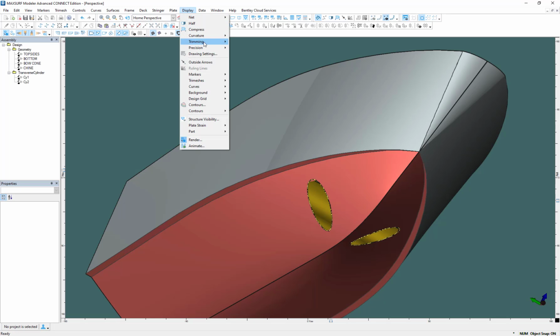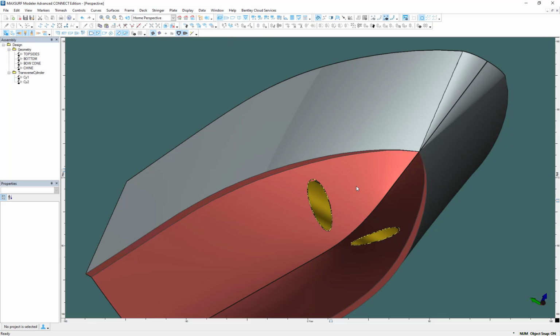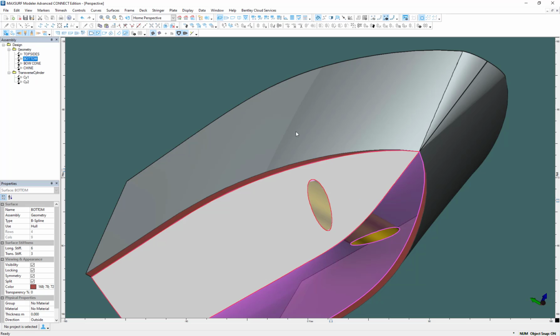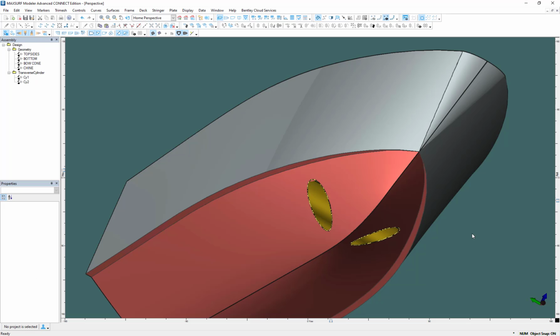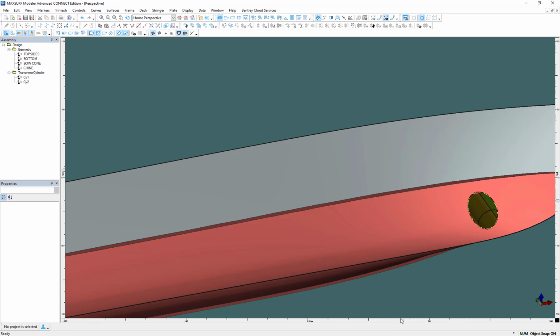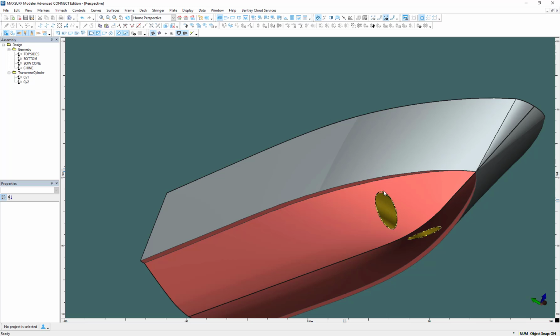Now, if you do have a situation where this start trimming untrim is not active, then you will need to go to display trimming and set it to trim invisible. So we can turn that display of trimming on or off if we want. So yeah, we need it on trim invisible to go and do this trimming. And here we currently have that trimming correct. So now we have that trimming as dynamic trimming.